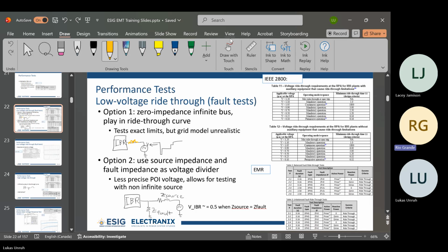So keep in mind that if you're trying to test it for the requirement directly, you're not going to get a meaningful answer. But if you're trying to do your own test bench, and maybe that involves multiple different depths of fault in a certain amount of time, and it's tripping offline always on the 5th fault or always on the 7th fault or whatever, that's also a good indication that maybe it's a model hard coding thing that is a problem, like Lucas mentioned earlier. It's probably just a hard coded value in there that says after blank.